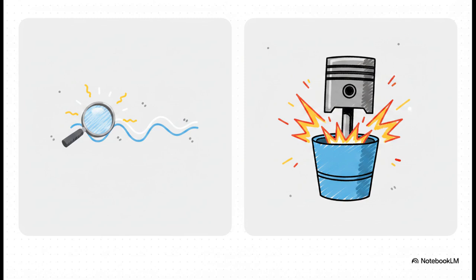Now, compare that to writing data. Sense amplifiers are used for reading. They detect tiny voltage changes. But for writing, we use a write driver. It uses a strong signal to forcefully override the bit line voltage, actively forcing the tiny trench capacitor to accept a new 1 volt or 0 volt charge. Reading is delicate, writing is forceful.